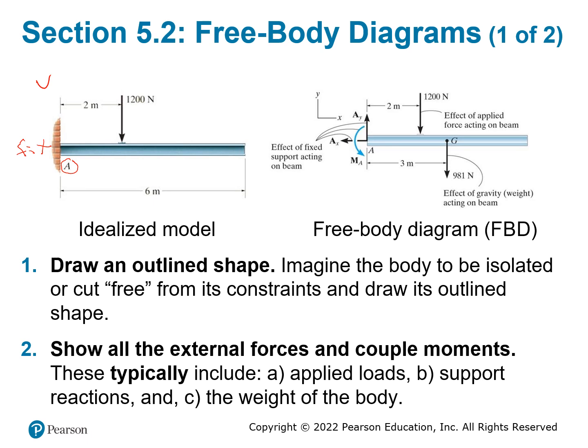If this is a fixed end, we are going to have a different reaction force when you do a free body diagram. When we do a free body diagram, we isolate the object and we cut off any of the connecting part, which is this part and here. When you cut that off, it can support a Y reaction, it can support an X reaction, it can also support a moment, because you need this moment to counter when you remove this fixed end, when you remove any of the support.